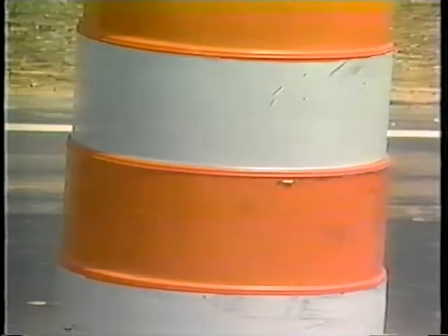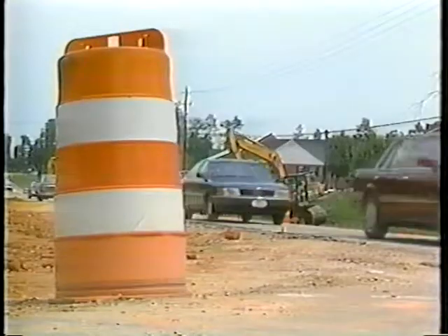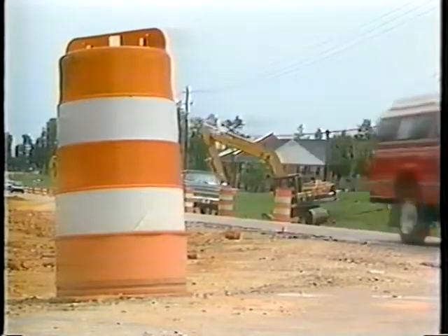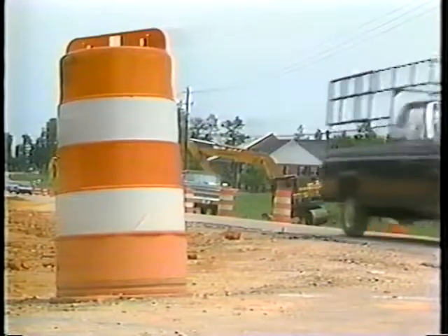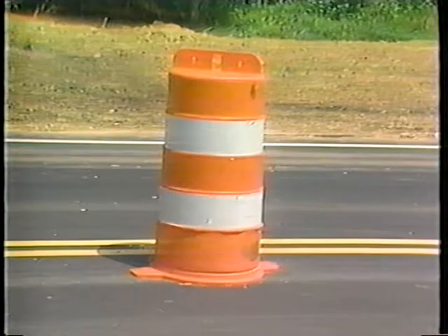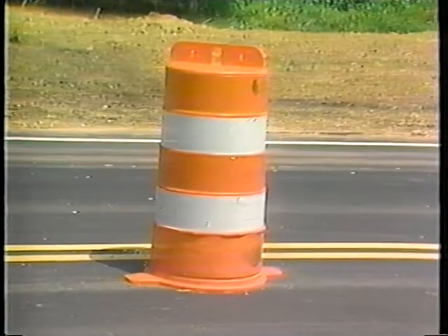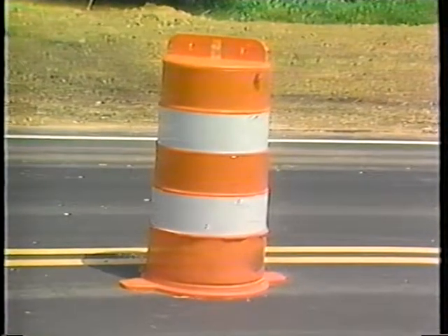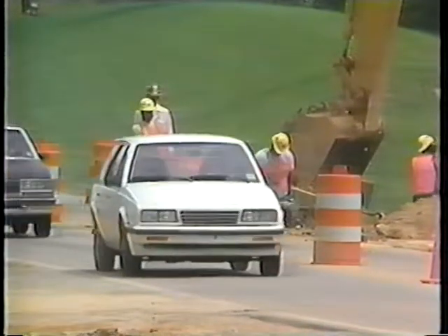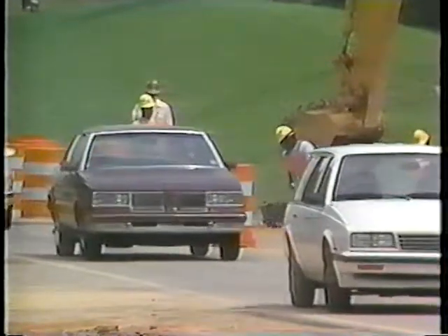The drum must have at least 2 sets of orange and white stripes, but can have non-retroreflectorized spaces up to 2 inches wide between the stripes. Drums must have a minimum width of 18 inches, regardless of orientation, and their tops shall be closed. Plastic drums can be nested, allowing for easy transport and storage.